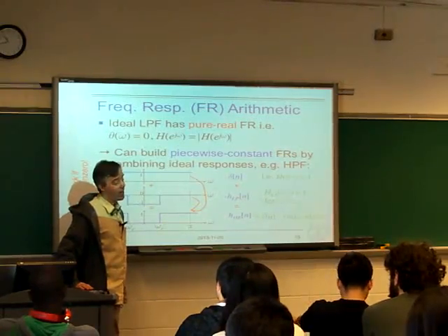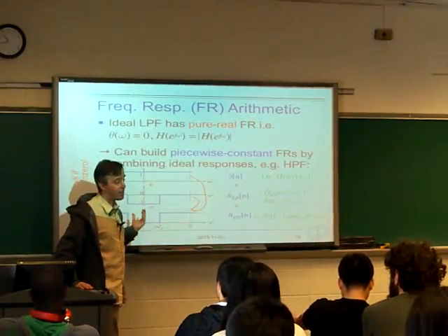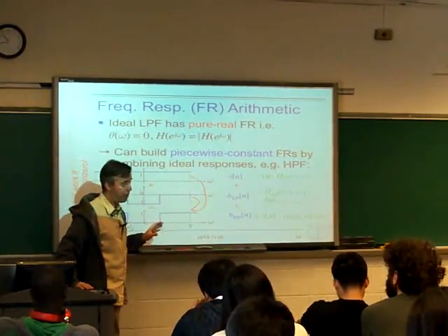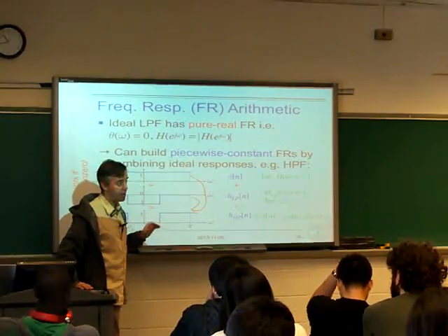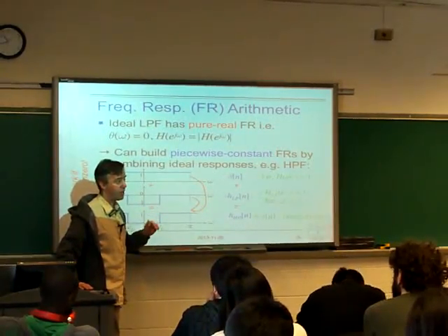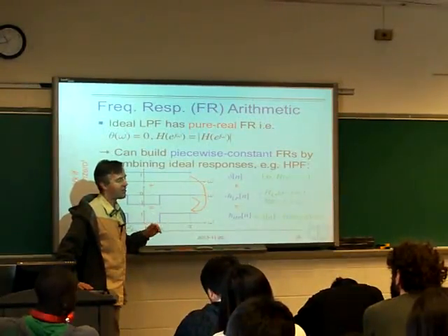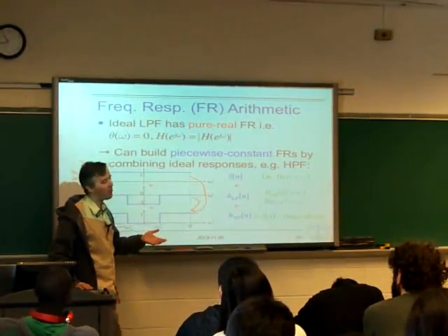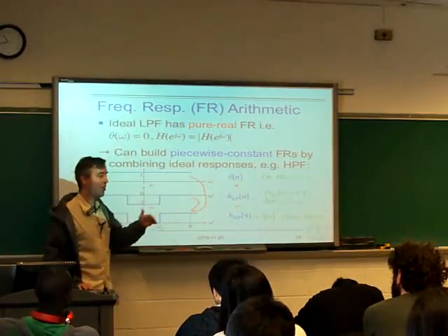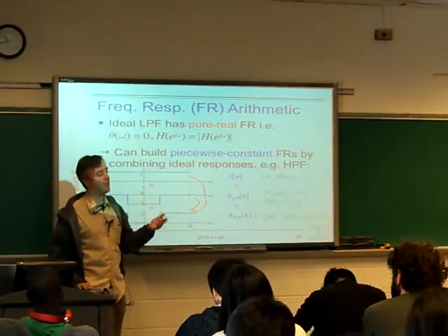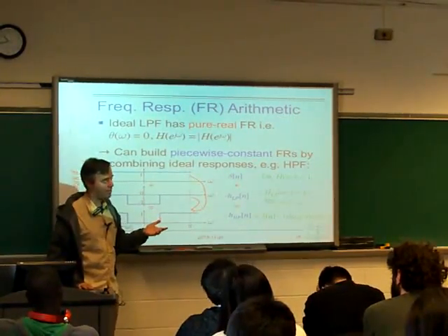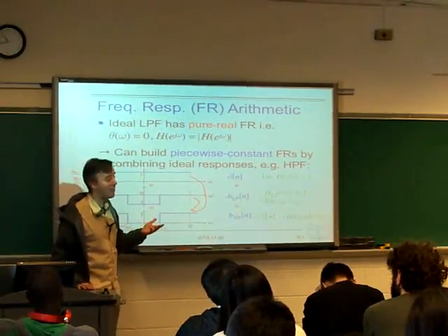If you care about phase response, the FIR filter is going to be much better because now we've got no group delay, right? There's no relative shift in. No, we do have group delay, but we've got no phase distortion. We've got no variation in the phase shift with frequency, no variation in the delay experienced with frequency.